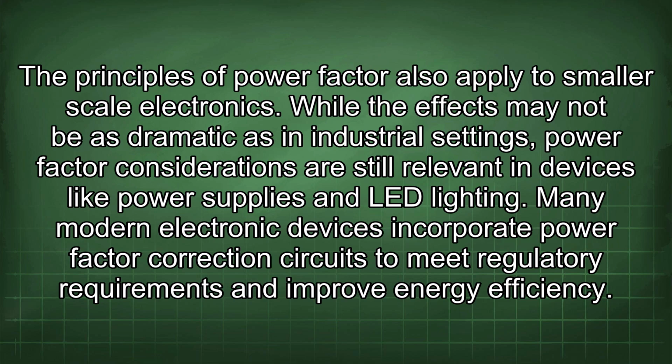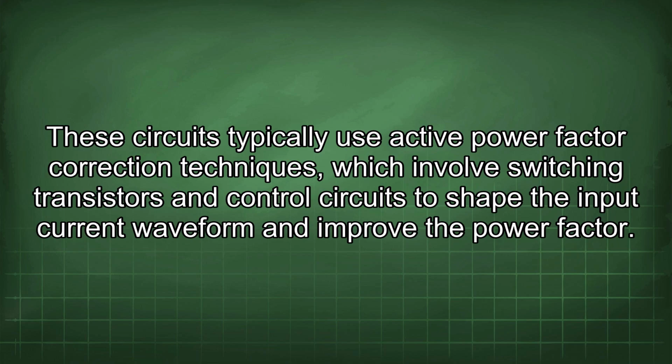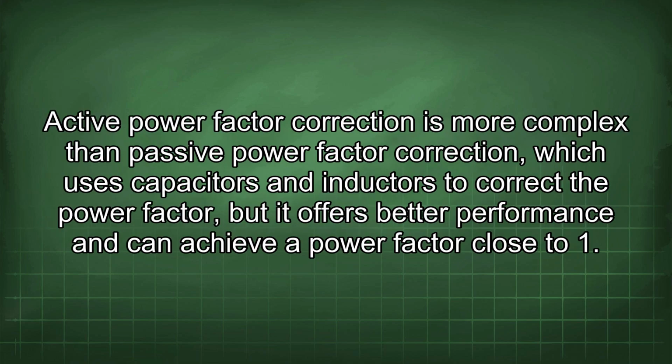Many modern electronic devices incorporate power factor correction circuits to meet regulatory requirements and improve energy efficiency. These circuits typically use active power factor correction techniques, which involve switching transistors and control circuits to shape the input current waveform and improve the power factor. Active power factor correction is more complex than passive power factor correction, which uses capacitors and inductors to correct the power factor, but it offers better performance and can achieve a power factor close to 1.